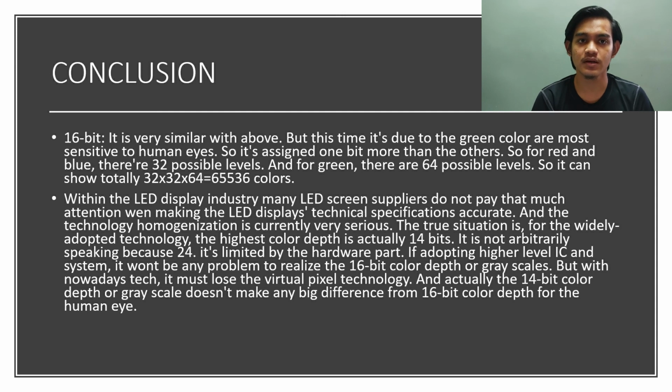Within the LED display industry, many LED screen suppliers do not pay that much attention when making the LED display accurately. Because the true situation is, for the widely adopted technology, the highest color depth for making the LED display is only 14-bit. Because it is limited by the hardware. If they adopt a higher level integrated circuit and system, it won't be any problem to realize the 16-bit LED display color depth or grayscale.